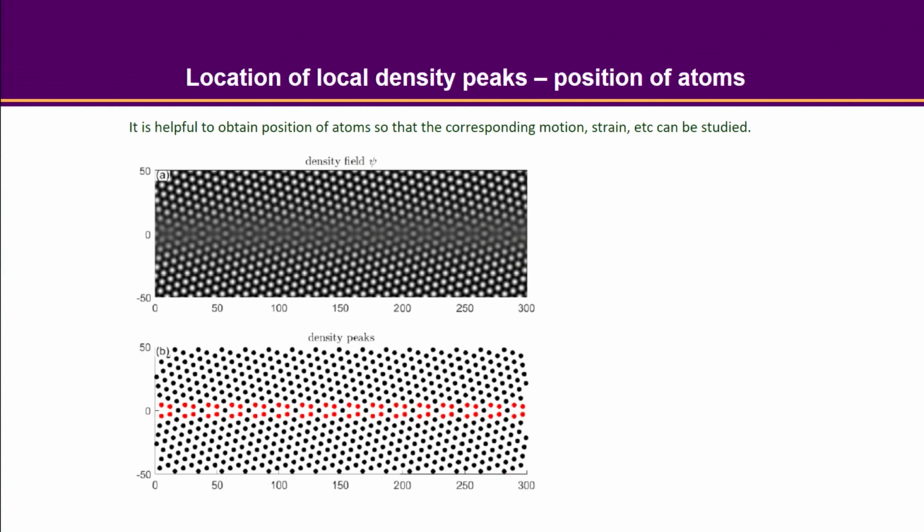So on the top of the figure is the density field you simulate, right? That's from the phase field crystal. So here you have psi as a function of space. You have these local peaks, and the density peak will drop down a little bit on these grain boundary structures, because the structure is so disordered, so you are expecting fewer atoms can be found around here.